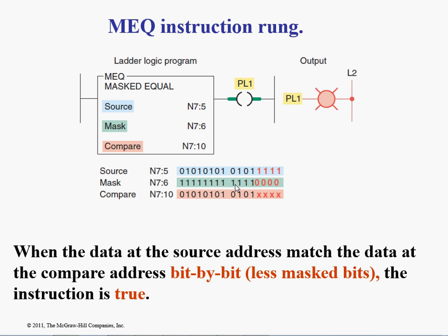I could program some conditions just using normally open and normally closed, which would probably be a better idea because a lot of people don't understand that. So it'd probably be a better idea to program some conditions to say that if you want to start when product A is active, then this limit switch has to be off, this limit switch has to be on, do normally open, normally closed, and then turn on a bit.